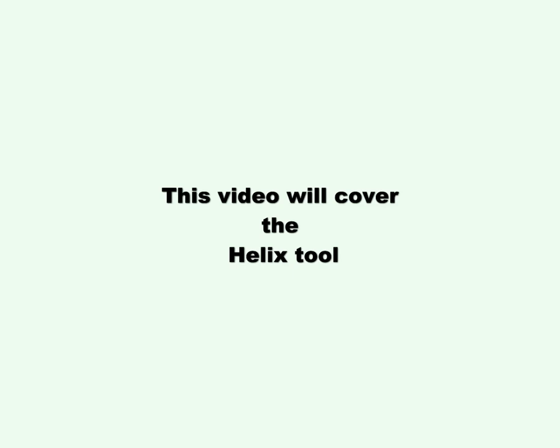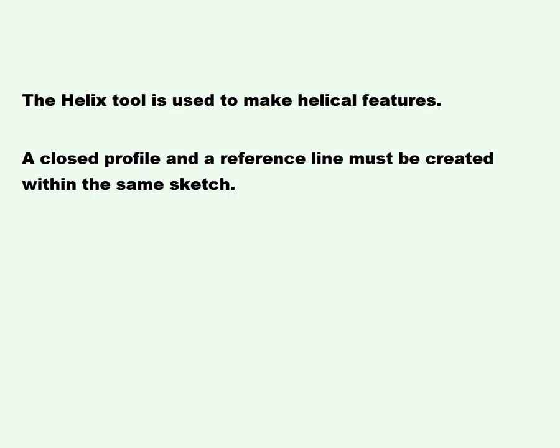This video will cover the Helix tool. The Helix tool is used to make helical features. A closed profile and a reference line must be created within the same sketch. The Helix tool cannot be used along a curved figure, nor can the default axis be used.